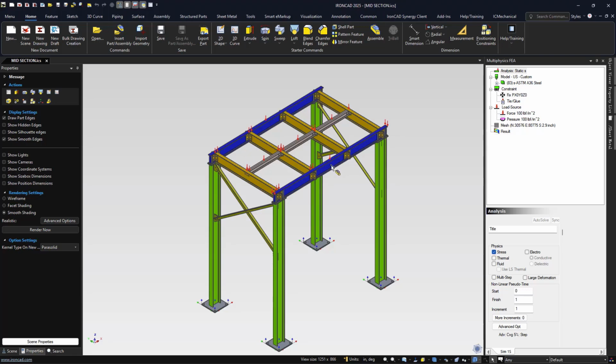I've also put another load on the side here, or normal pressure, to basically push it in. Think of something running into this, some other lateral load going onto this, to see how this will adjust with this brace here. So this brace is mirrored on the other side, and we have parameters that drive how far it is from the top of the green steel beam here, so it can move down for the values. And then we also change the angle of this to adjust the strength and rigidity of this platform. So that's what we want to know.